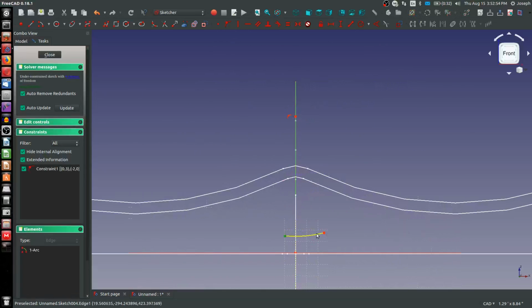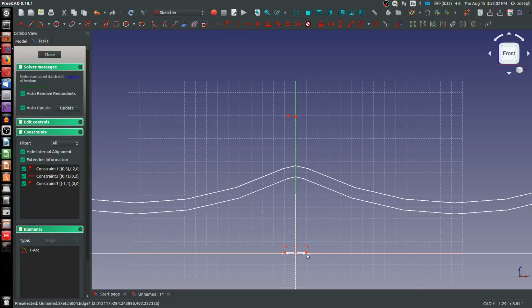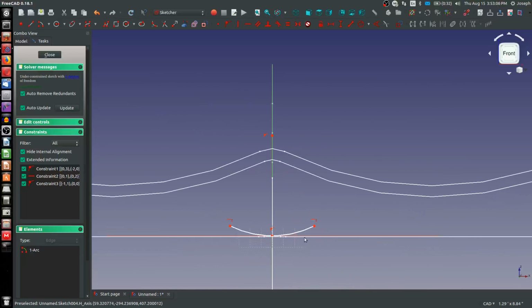We're going to make an arc, choose these 2 points and say H for horizontal. Now choose the origin, and that forces it to make it just straight, coincident with the rim point instead of on an end point. What radius to give this? I'm going to give this a radius of 24 inches, so it's a little bit more flat.